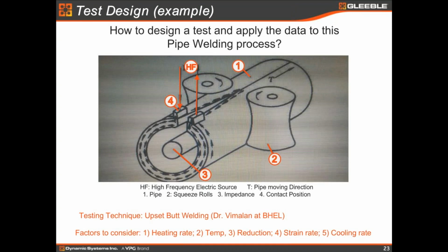U-shaped processing of the pipe welding. Normally, it's just a conventional welding process. You just U-shape it and squeeze it together, and then just weld along the straight line. But now this is a new technique. They're using high frequency electrical heating to do the welding without electrode materials at all. I believe it's much more efficient, it's much more economical and fast.